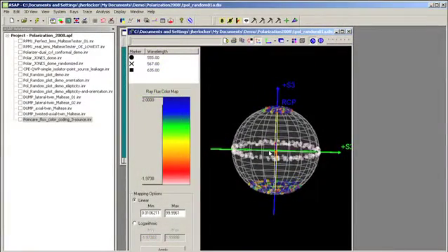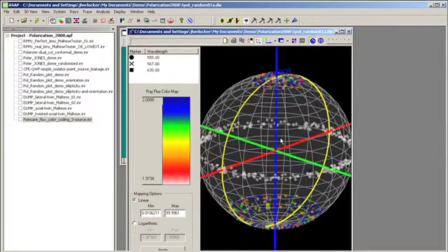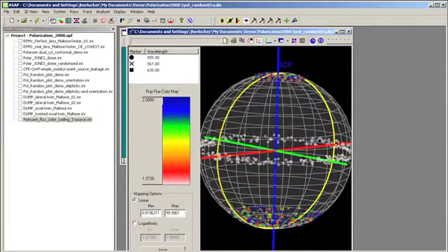Finally, the Poincare sphere visualization tool in the 3D viewer enables graphical examination of polarization states. Each polarized ray is identified by its polarization state, wavelength, and flux. Location on the sphere shows the polarization state. Wavelength is given by the marker shape, and flux may be shown by the color. The flux mapping can even be done in either a linear or logarithmic way, and limits may be set to